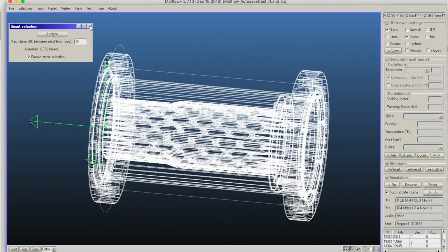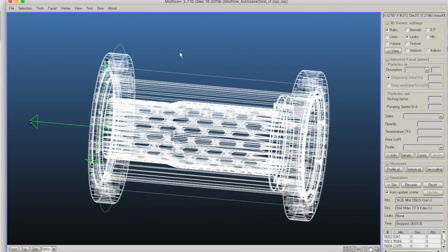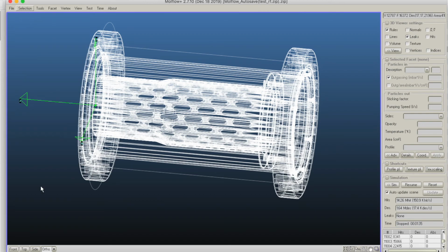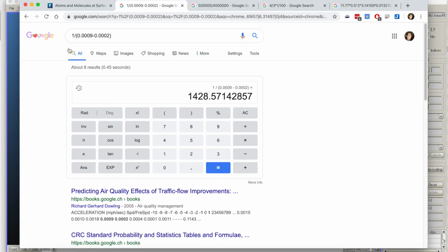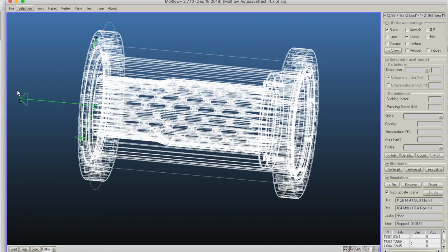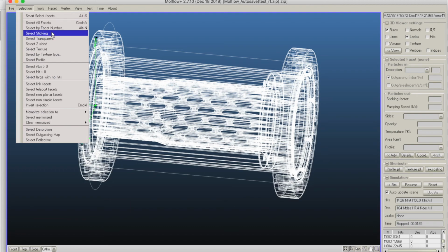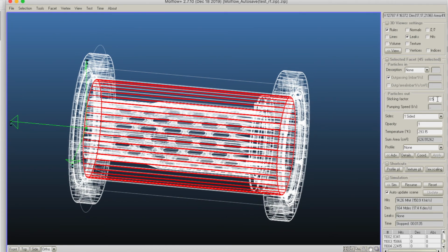And finally, it's always great to check if our calculations stand up to basic physics equations. So far, I have basically divided the total outgassing by the pressure difference. You might remark that in the beginning we set a sticking factor of 0.5, which corresponds to about 3.7 thousand liters per second. Don't forget that this is a large area, so the high pumping speed is actually warranted.